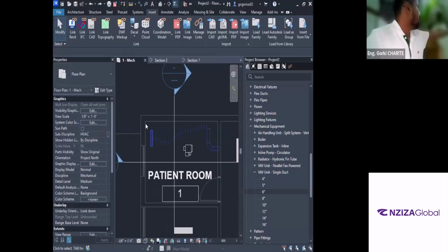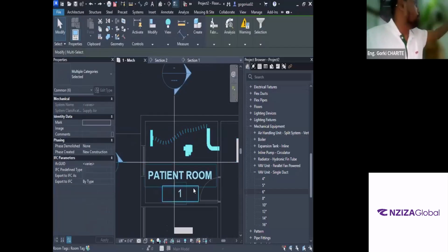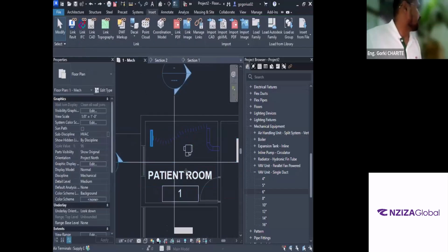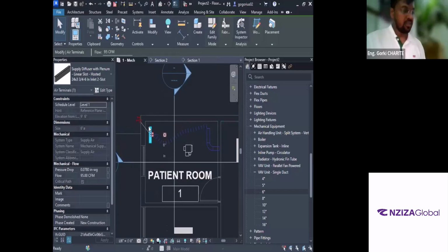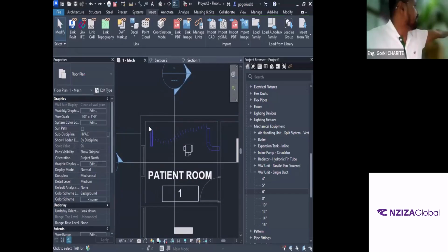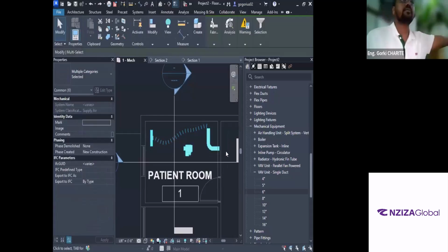This is one more tool that you can use in Revit. For the elements that you want to view in 3D view, click in a blank space, click, hold, drag. That will select all of the elements. Don't directly click on this element and drag it because that will move its position. Click in a location that is not inside, click, hold, drag, and then it will get selected.